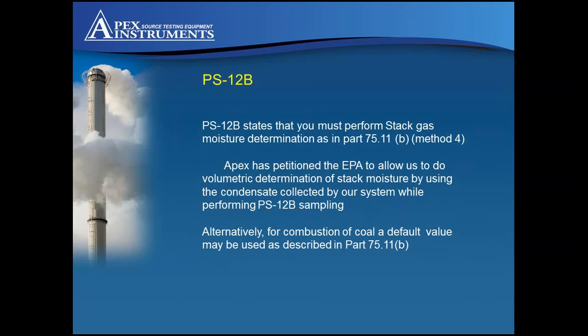You also can use a default value based on the type of coal that you're burning to record your actual moisture. The problem with that could be you might be reporting at an invalid rate compared to what you really are, and either reporting higher or lower mercury than what you really have.